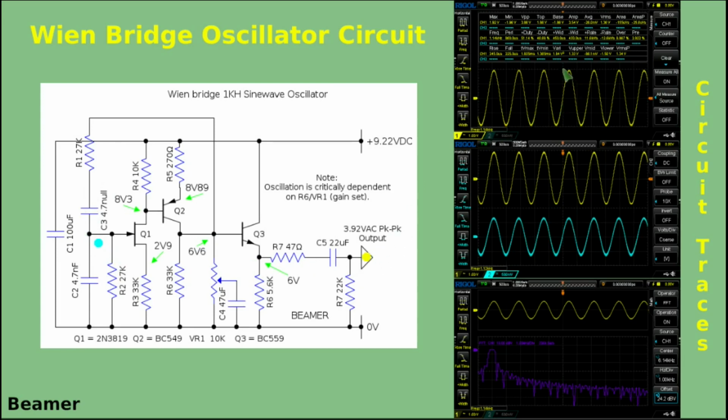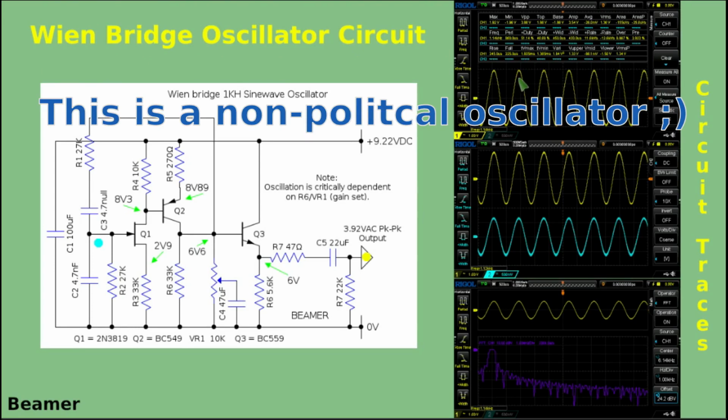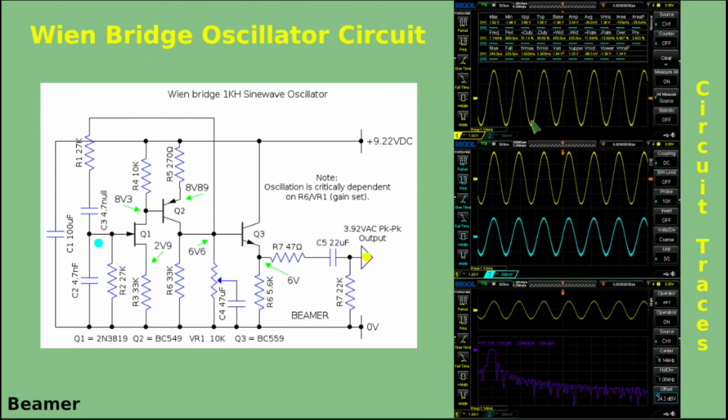At the top here, the first trace, you can see the output quality from here, the yellow spot, and you've got additional comprehensive information at the top here. You can see that the quality of this sine wave is superb. It doesn't lean to the left, it doesn't lean to the right, it's not over peaky, negative or positive, and there is no clipping going on here. It probably is not the best that can be achieved, but it certainly is the best that I could achieve.